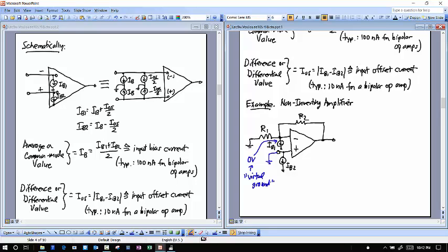And so if that's a virtual ground right there, then that says that there can be no current flowing through R1, right? So IB is not going to want to take any path through R1 there. So let me just write that there. So I'll just say, therefore, current cannot flow through resistor R1. However, current has to flow because I've got that IB1 right there.